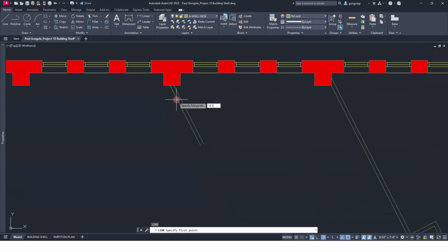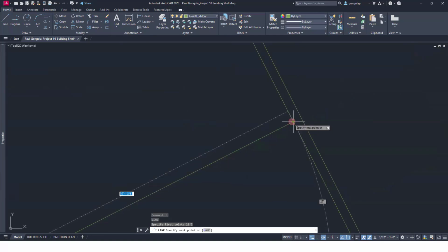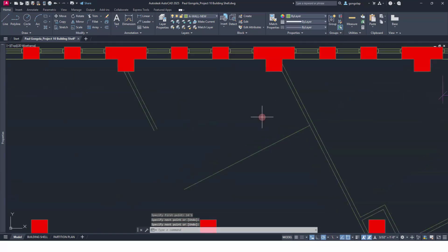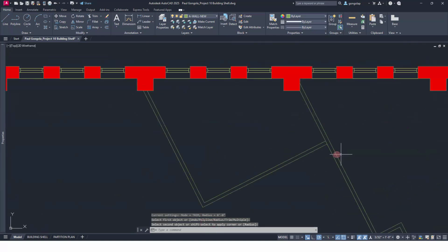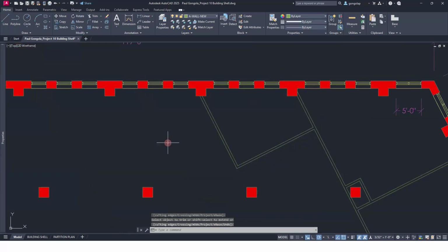16 feet one. And then I'm going to come up 27 degrees or go perpendicular. There's my perpendicular right there to that wall. And I'll offset 5 inches for my wall. And then I can just fillet these corners here. Easy peasy. And I have my wall. While I'm here, I'm just going to trim this just to make it look a little more professional. Okay, beautiful.